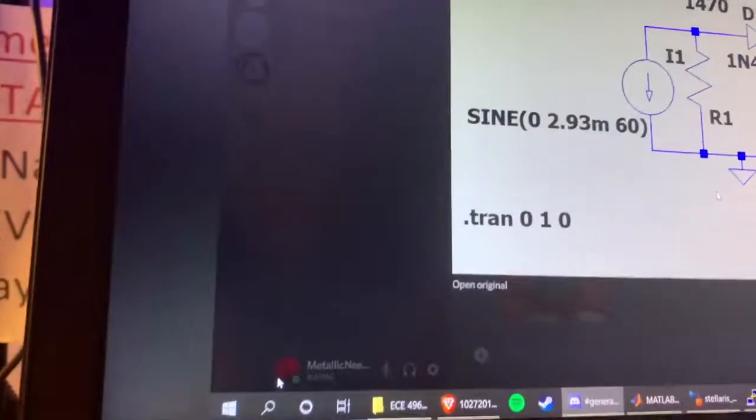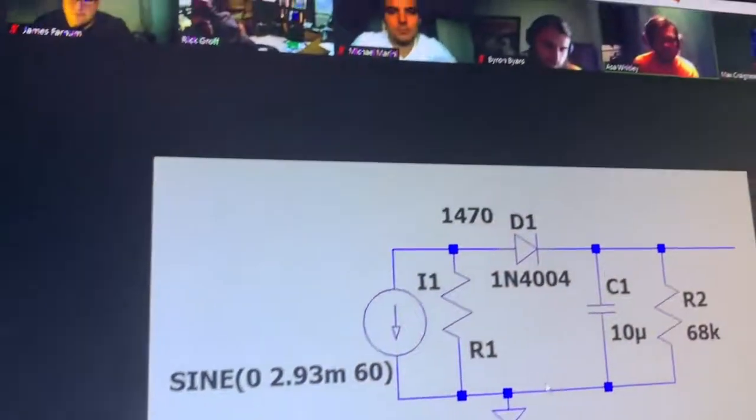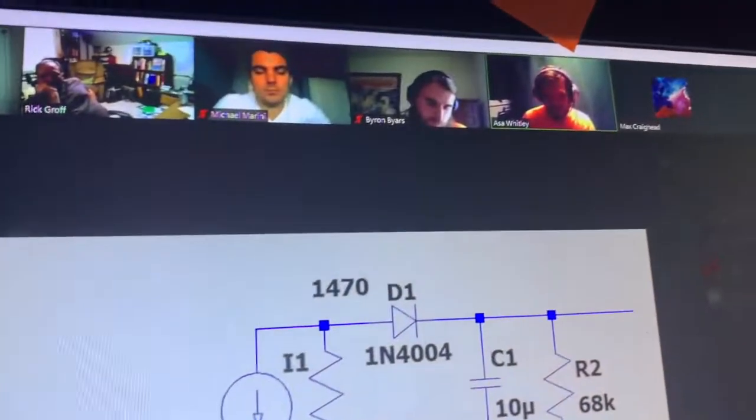Moving on to the current transformer subsystem, our loads in this case are AC, but our microcontroller reads in DC voltages. In addition to that, a maximum voltage that the TIVA can read in is 3.3 volts. In order to correct this, we use the full wave rectifier with a low pass filter that changes our AC signal into a DC signal no more than 3 volts.